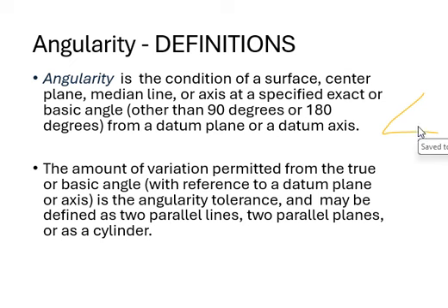And of course, we always give a range. The true angle can vary, and every time you have a range for a geometric characteristic to vary, we call that tolerance. Since we're dealing with angles right now, we call it the angularity tolerance. Meaning the angle can vary in that range. We will tolerate the angle measurement variation to be in that range. So that's all the steps.